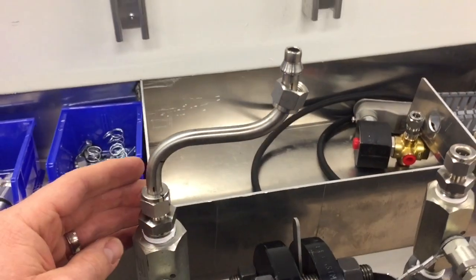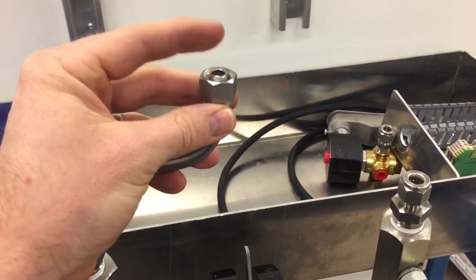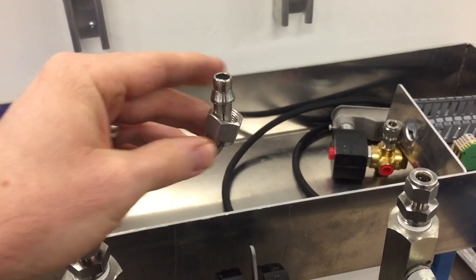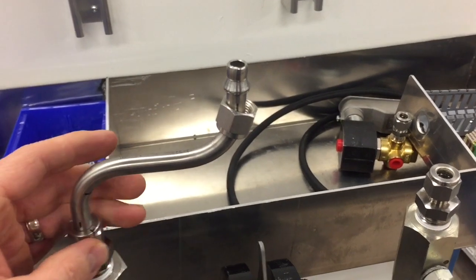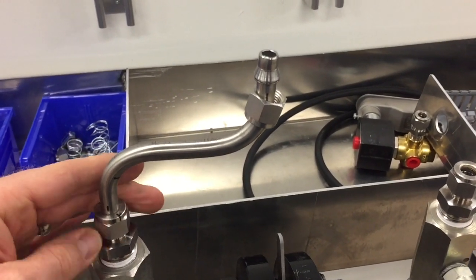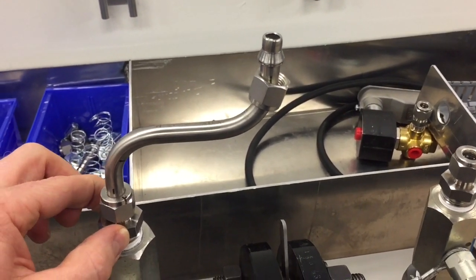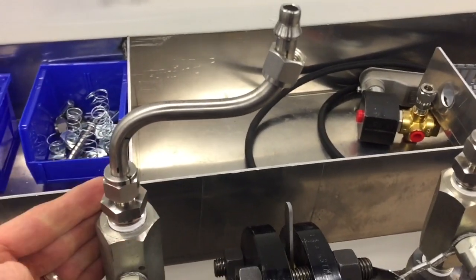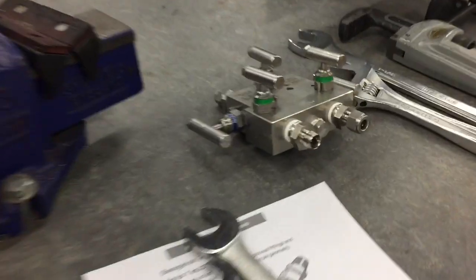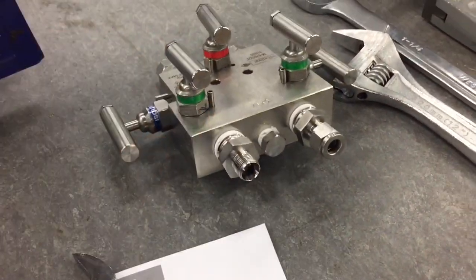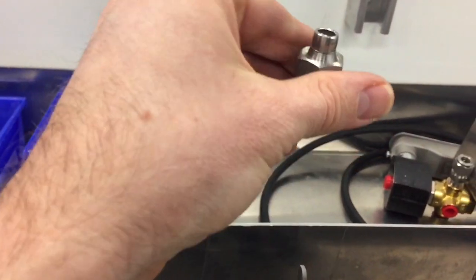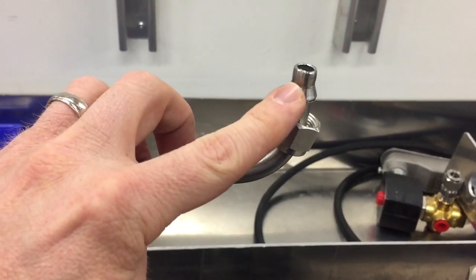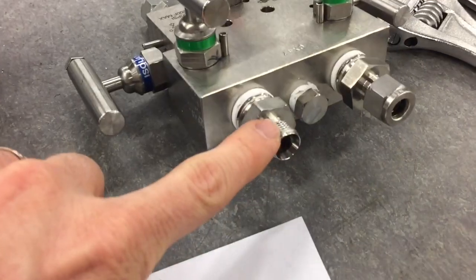One other thing I want to point out before I install the 5-valve manifold: this nut and ferrule I was able to set just by using this fitting down here. I've got to tighten this still, I see. Sometimes it's more convenient to use a fitting that's nice and easy to work with. It's kind of held in place already, right? Whereas the one over here on the manifold might be kind of tricky because the manifold's kind of loose unless we threw it in a vise or anything like that. But I just wanted to point out that you can set these fittings in any other fitting. They're interchangeable. Now I can go and install this on the bottom here of the 5-valve manifold.